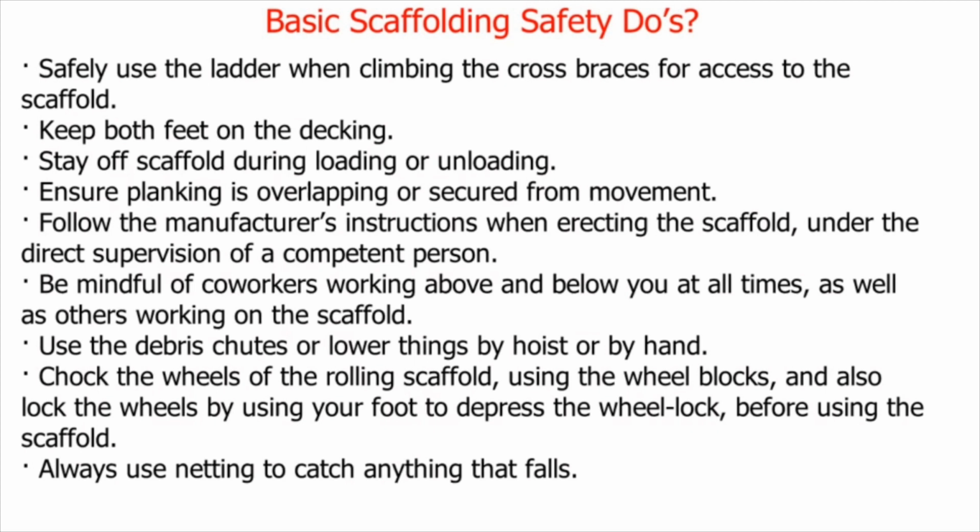Safely use the ladder when climbing the cross braces for access to the scaffold. Keep both feet on the decking. Stay off scaffold during loading or unloading. Ensure planking is overlapping or secured from movement. Follow the manufacturer's instructions when erecting the scaffold, under the direct supervision of a competent person. Be mindful of co-workers working above and below you at all times, as well as others working on the scaffold.